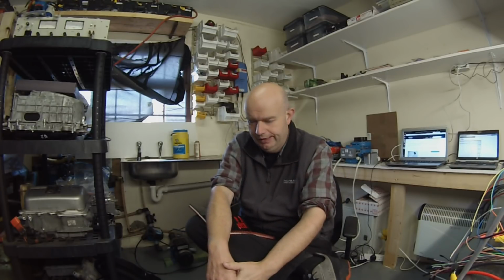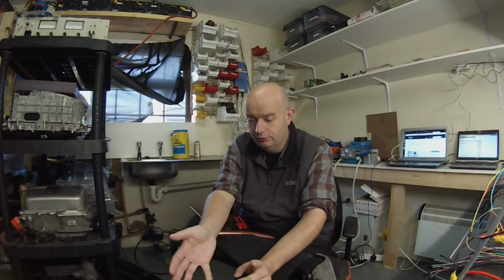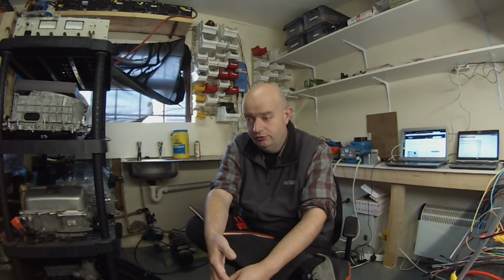So with pre-charge on selected, I can comfortably say that during the week that I spent with the vehicle, we triggered at least 200 overcurrent events during testing, during all manner of driving, be it on the road, on axle stands, dynamometer, racetrack, everything, and the inverter did not fail.